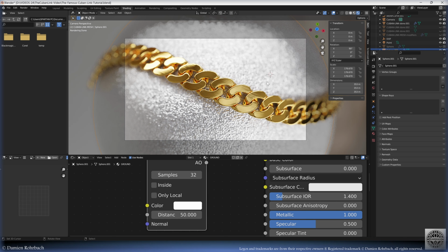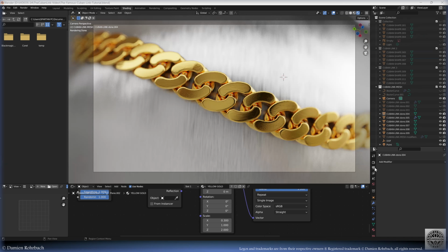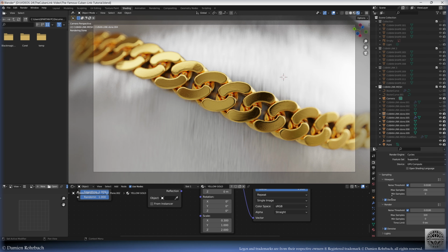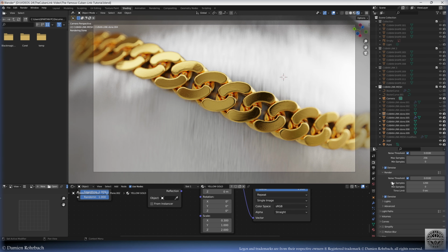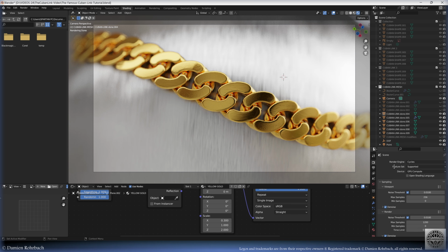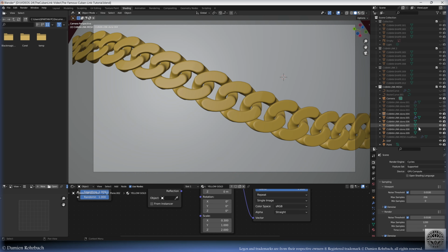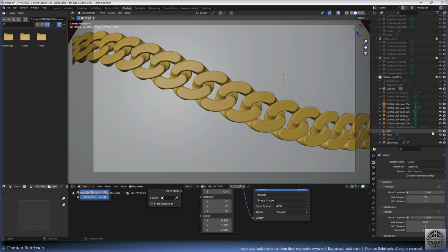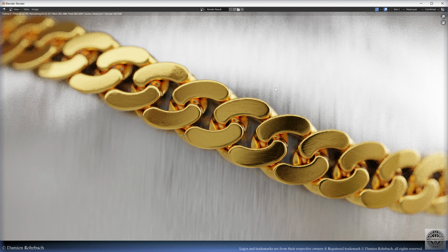We need to prepare the render parameters. Resolution 4K. Now render 1200 samples. Denoising OpenImageDenoise is more accurate, a bit slower but better quality. Performance depending on your hardware. Note that tiling is generally slower. We are ready to render. Go to solid mode. Check that all your objects are ready for rendering. Hit F12. They have told me that this is the moment of happiness for humans.